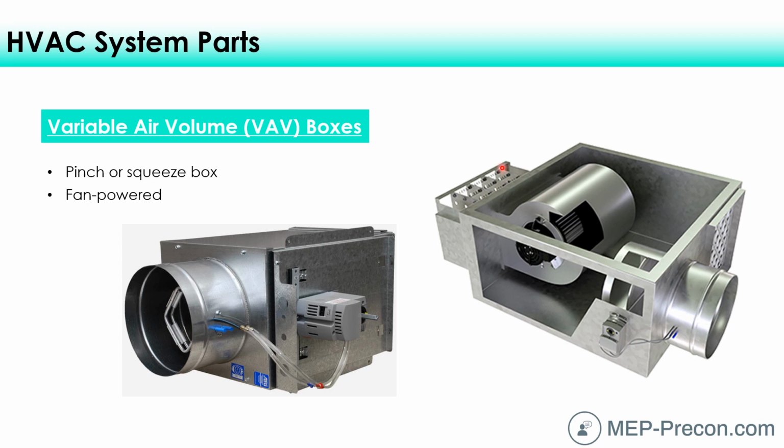So it heats up, and these little elements in here get red hot, kind of like the color of the laser pointer there. And we exchange heat between the air and that little toaster coil heat exchanger there, and that's how we reheat the air back up. So anyway, those are kind of the parts of a VAV box. There's some terminology. There is what's called a pinch or a squeeze VAV box. Still variable air volume. The air passes right through here, and we control the volume with this little actuator controlled by the thermostat.